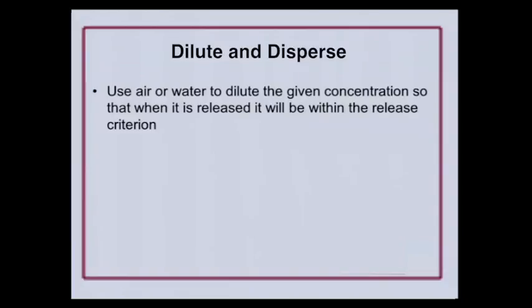So if I take my volume of radioactive and I release a small amount of it over time in that discharge volume, I have diluted it. My microcuries per cc out here is well within the limits permitted by my license. My total curie content is still there. I mean, I still have a total curie content in this volume here, and my total curie content that winds out there is the same, and that is limited by my tech specs and my license as well. So it is a method, it's an approved method for disposal of liquid rad waste. It's a dilution process.